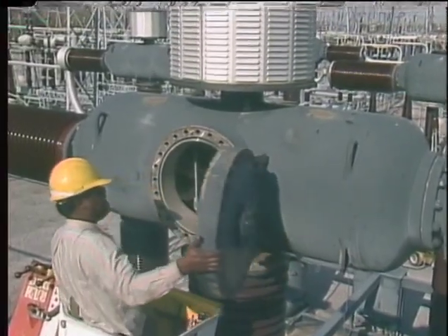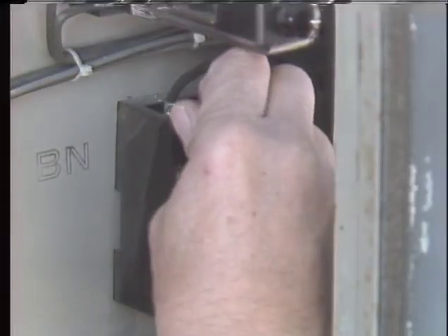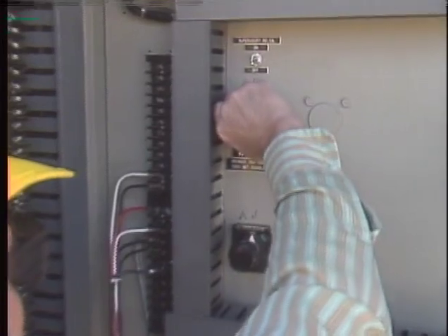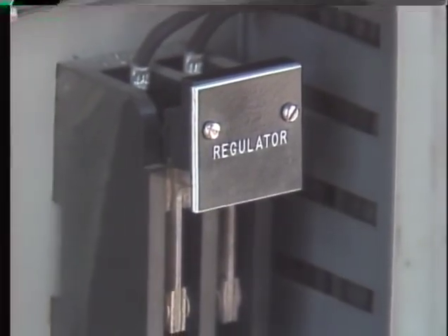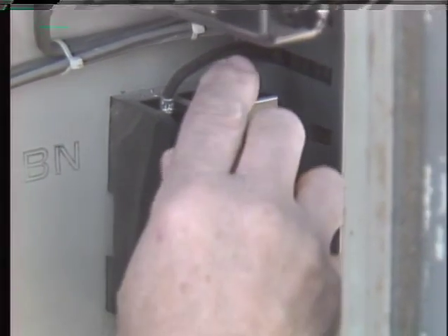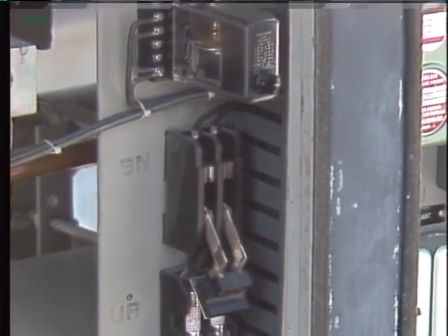After the interrupter maintenance is done, the heads are closed back up, and system pressure is restored to normal. After the pressure is restored, the breaker is closed. Air pressure is allowed to return to normal again. Then the pressure regulator is de-energized so that breaker air consumption can be checked.